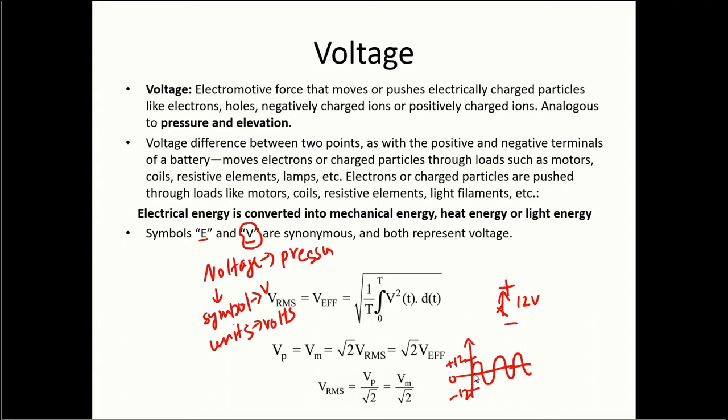So you can see that the wave in alternating current is oscillating with respect to time. On the y-axis you have the levels, on the x-axis you have the time. Since the voltage values are varying with respect to time, you need to represent that with a constant term, and that's when we make use of something called voltage root mean square, and we'll get into that in the coming slides when we get into AC circuits.